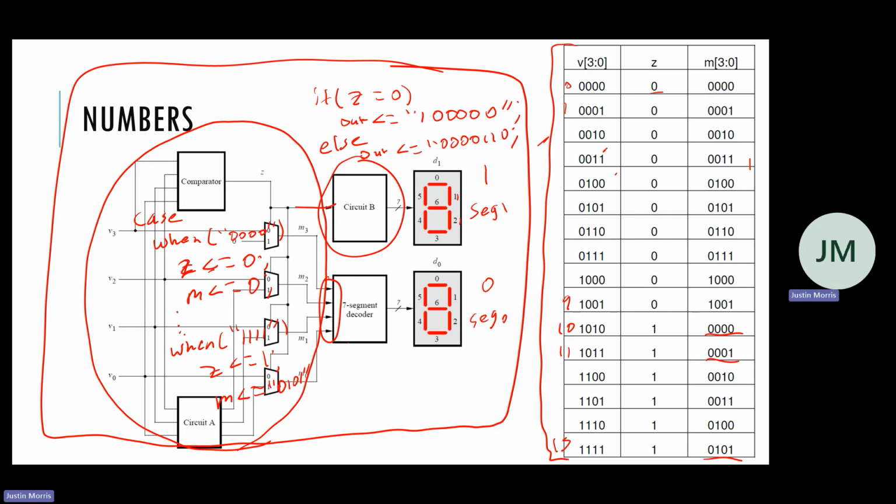So it's the 7-bit binary outputs that tell the display which one of these segments to turn on. If it's 0, it's on. If it's 1, it's off. So we have 0 through 6. The topmost bit is off, so this one is off. Everything else is on, so it's displaying a 0.